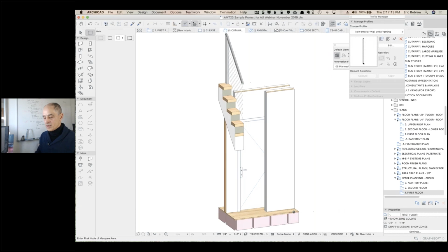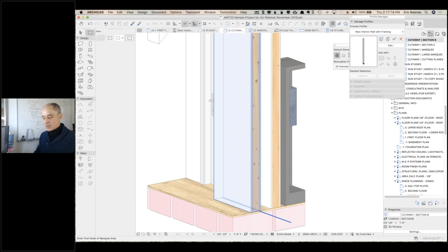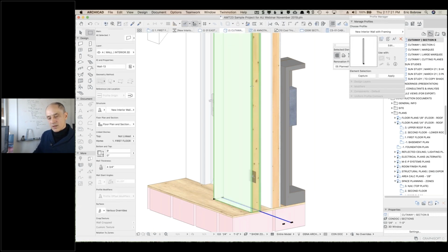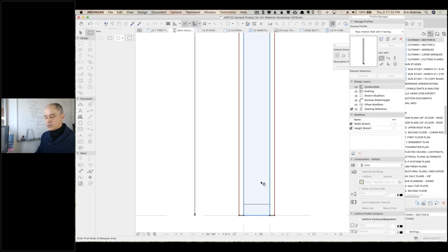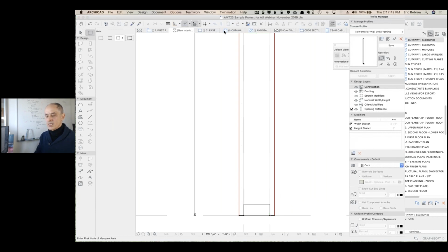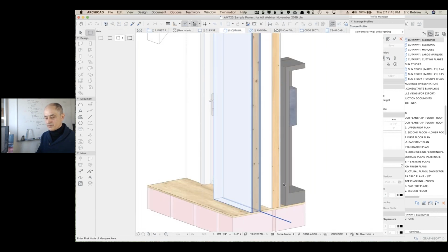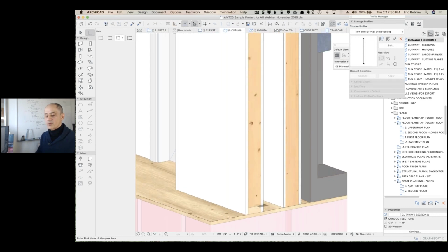All right, so we can see here this is not showing. This is the new interior wall there. So what is going on? It probably is using a similar one there. Let's go and edit this, and, oh, I know, this main part hasn't been pulled back, so I need to pull this back here. And let's just say save this, and then we'll go to that cutaway, and now you can see where we've got some framing, but I'm not seeing the cut line.